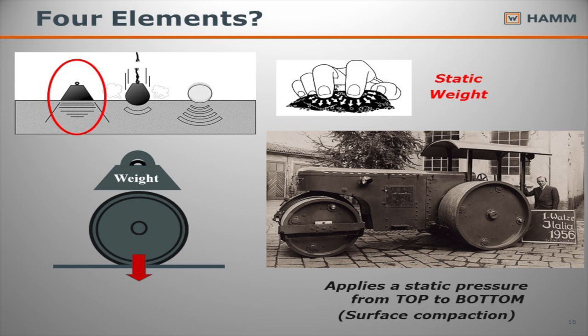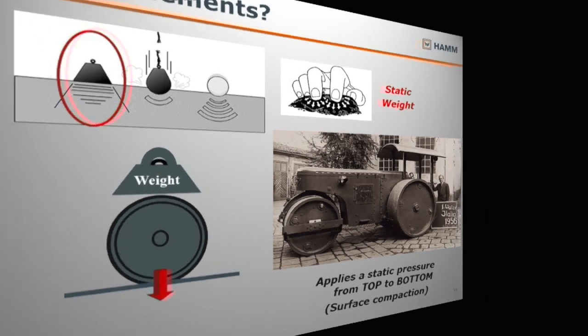The main reason why is years ago, the mixes that we had had a lot of marbles in them. So they were very easy to compact. And the three-wheel rollers had a lot of PSI per drum, and it was easy to compact the mix. Nowadays, we got a lot more fractionated materials in there, and we need a little bit more than just the static weight to get the compaction process down to the air void content we're looking at.